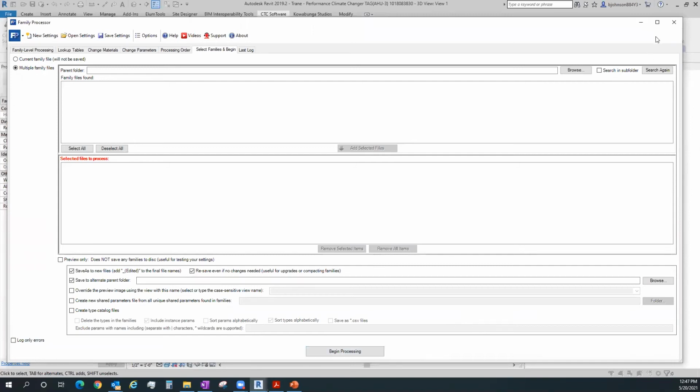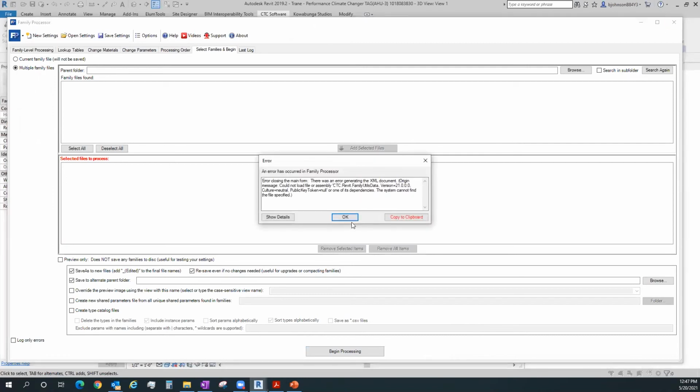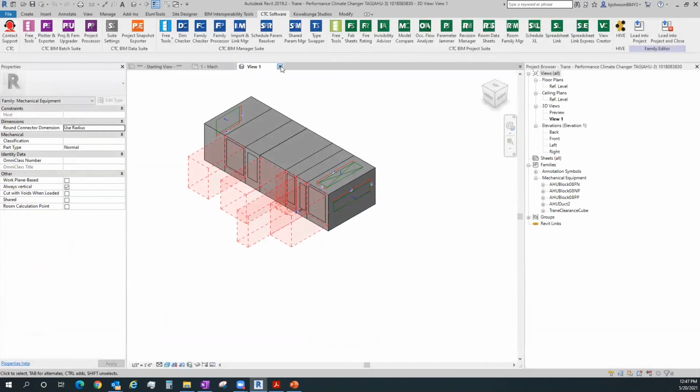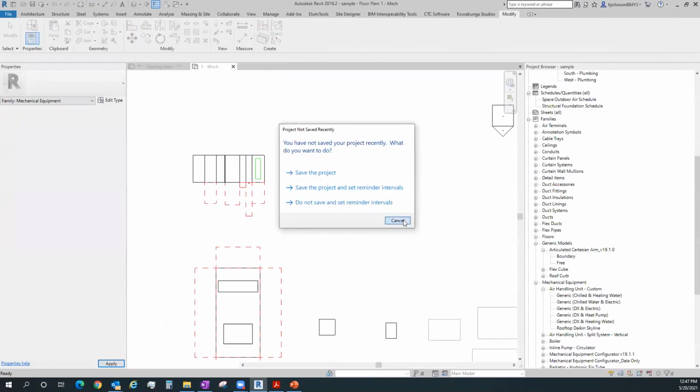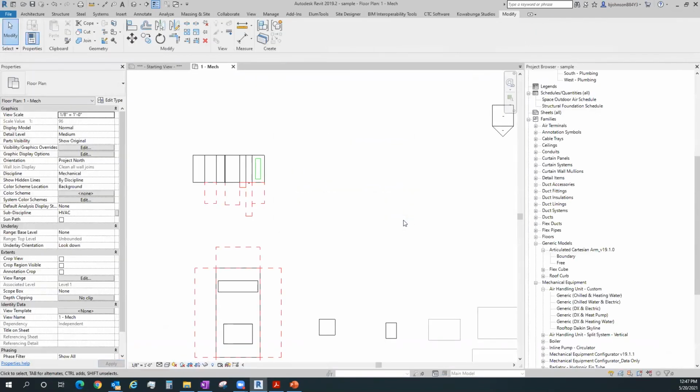So when it gets down to the nuts and bolts of what we are using placeholder families for, occasionally we will start and make a placeholder family that does get replaced. So this would be potentially a LOD 100 kind of a scenario, and replaced with something else that is more specific to my actual needs later, because maybe I either didn't know what I wanted, or I'm just guessing size, maybe because I'm in SD or DD and not really fully ready to commit to a manufacturer or some existing content that really is out there.